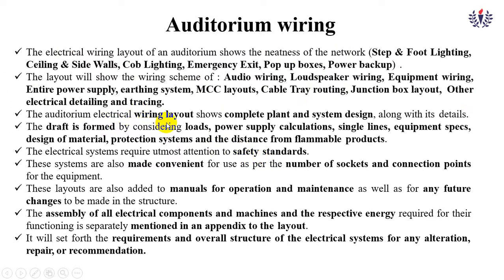The electrical auditorium or digital auditorium should have a complete layout or design, and based on that we should calculate the load, power supply calculation, single line diagram, specs, everything should be categorized. And there should be a fire alarm system for safety purposes, and a fire extinguishing system for safety purposes.